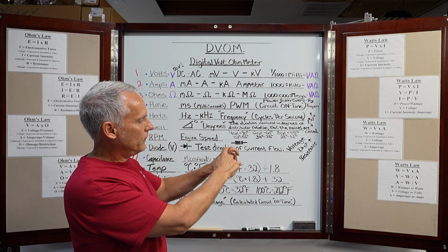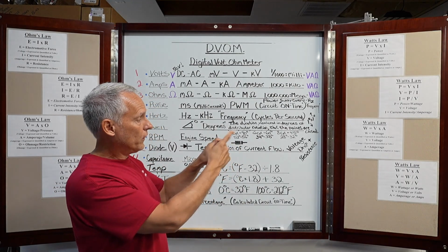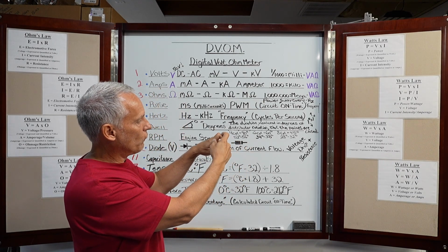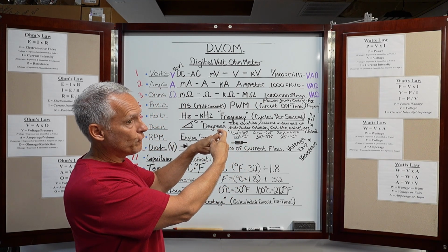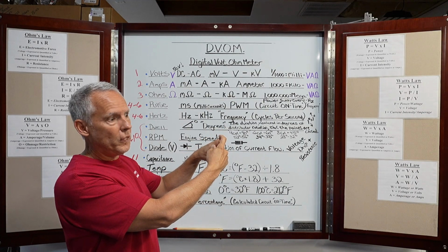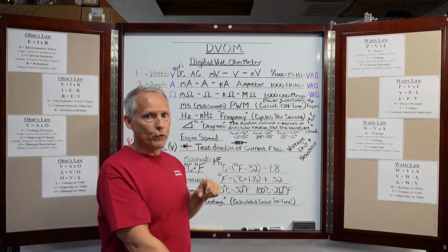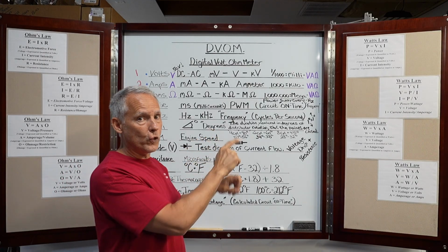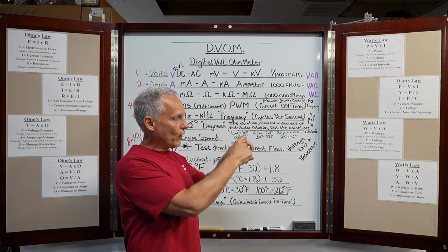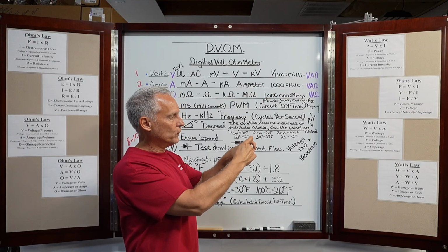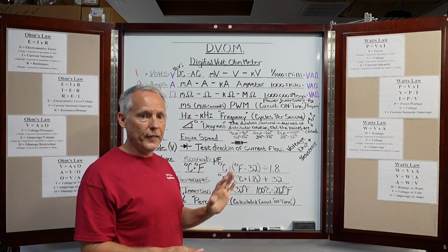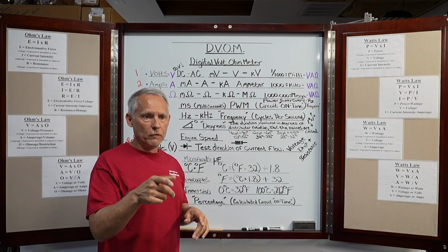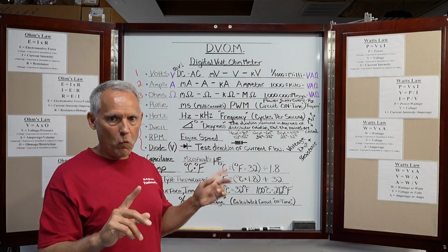So 1 degree is 1 degree at the crank. But the reason that the crank turns twice as fast is because if it's 1 degree, as it comes around, it opens a half a degree sooner. 1/2 times 2 is 1. So a 1 degree change in dwell is 1 degree of timing. A 2 degree change in dwell, it opens 1 degree sooner, closes 1 degree later. A 2 degree dwell difference is going to be 2 at the crank because it's 1 open, 1 closed. That's why it is double. You're right, but you're not thinking about the opening event and the closing event, right? So that's the reason why they're equal, 1 to 1.